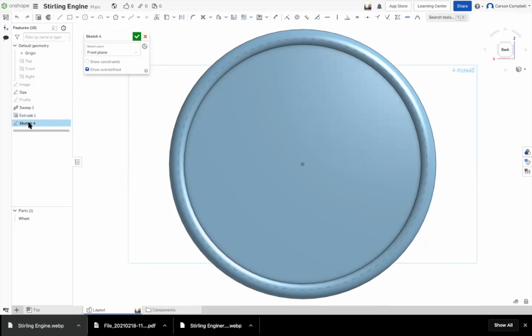So everything you do is based on something. What I just asked, what is this based on? That's referred to as the reference for sketch 4. The reason we use this terminology is because that's what's inside the manual. Everything about solid modeling are references. Anytime the system cannot figure out what a reference is, that's what the red is in the feature manager tree.